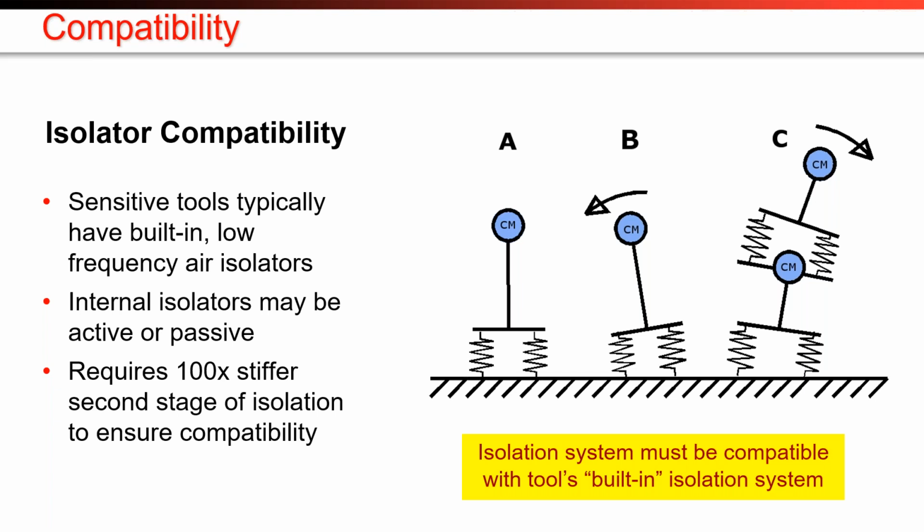So really the takeaway is that with vibration isolators, even a good vibration isolator can be counterproductive if it's being stacked with another vibration isolation system and it's not inherently compatible.